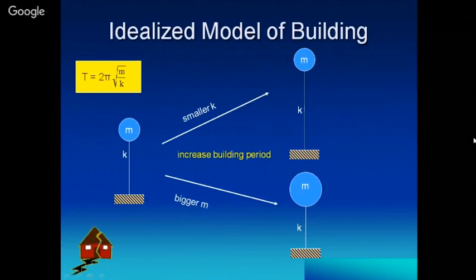If we do not have computer modeling, we can do the analysis manually. How do we idealize a complete multi-story building into a simple structure? We take the columns and their stiffnesses at the slab level.